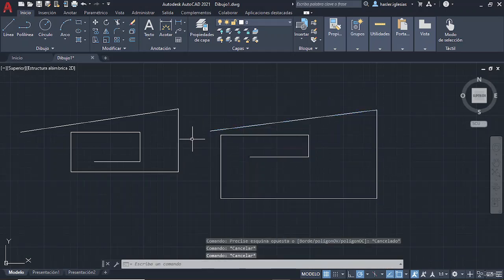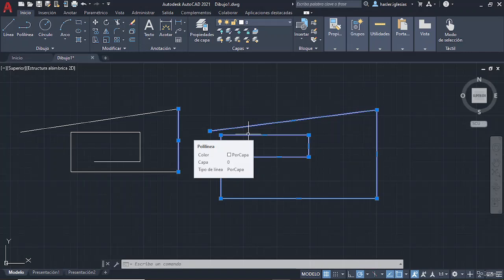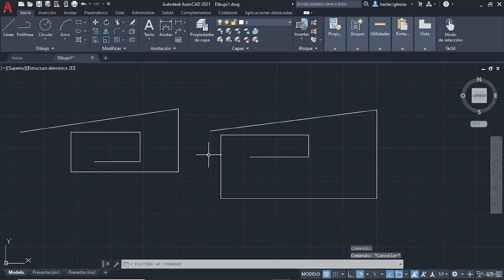Okay, well, look at something interesting. We are used to that when you click something, and you then click another thing, the first selection disappears, and then you have just selected the second thing. In AutoCAD, the selection does not disappear. You can select different things consecutively without having to do anything. So if I don't want to select consecutively, I have to press the escape button. Okay, so I can select this one, press the escape button, and then select this one, and I can move it as we already saw. This is the main difference.